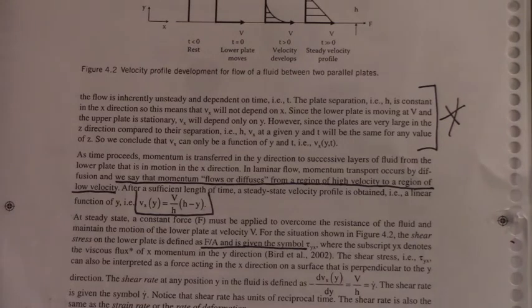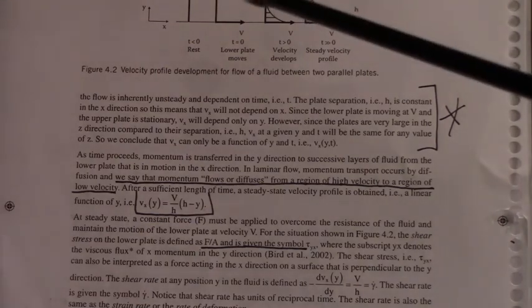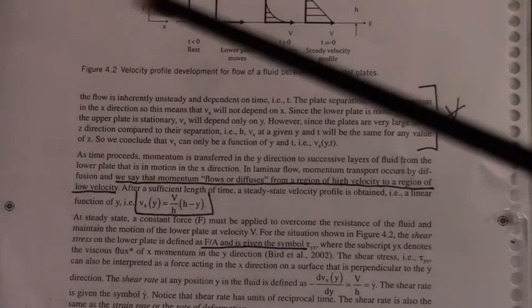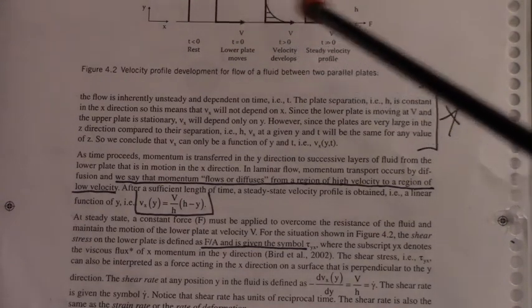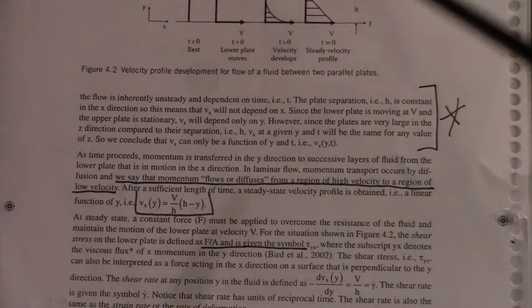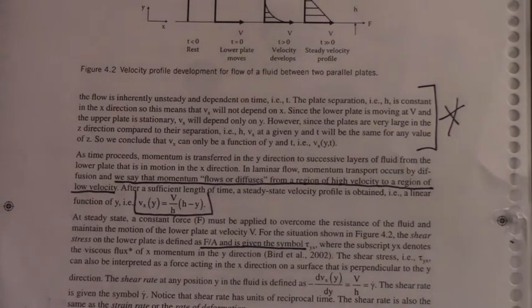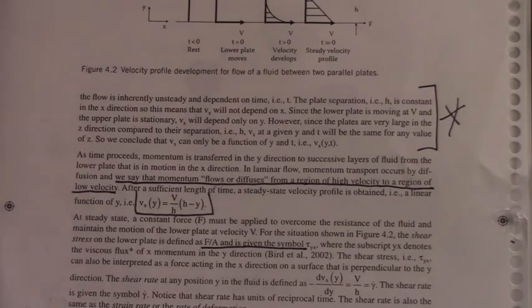So in a physical sense, the shear rate acting on this fluid or acting on a deck of cards would just be the velocity of the surface divided by the thickness of that layer. That would be your shear rate. If it was a deck of cards, it'd be the velocity of your hand moving across the cards divided by the thickness of the card. That's your steady state shear rate.